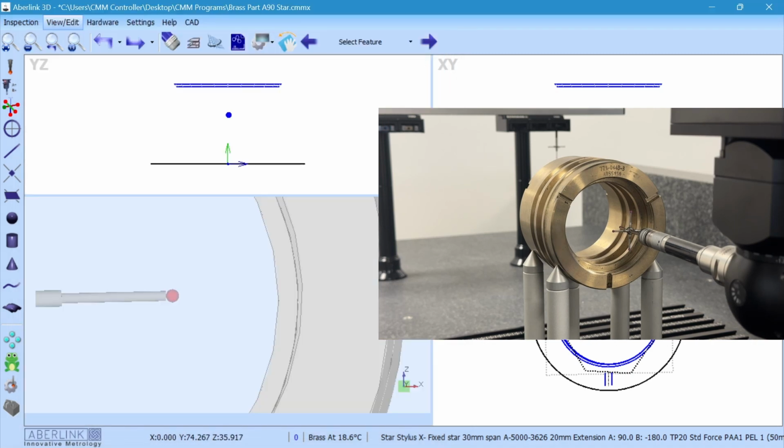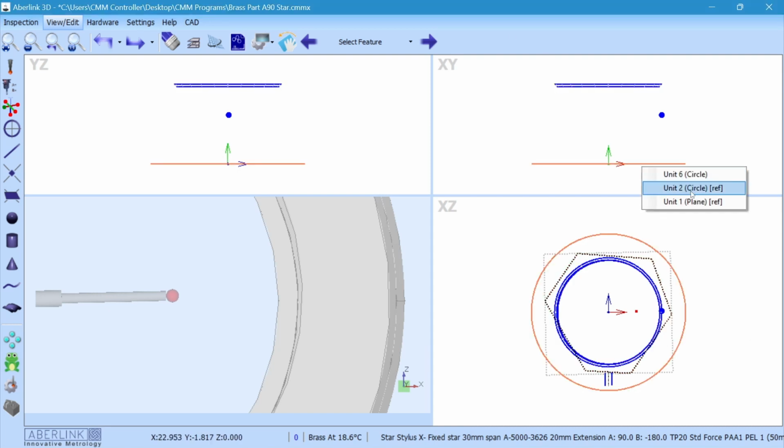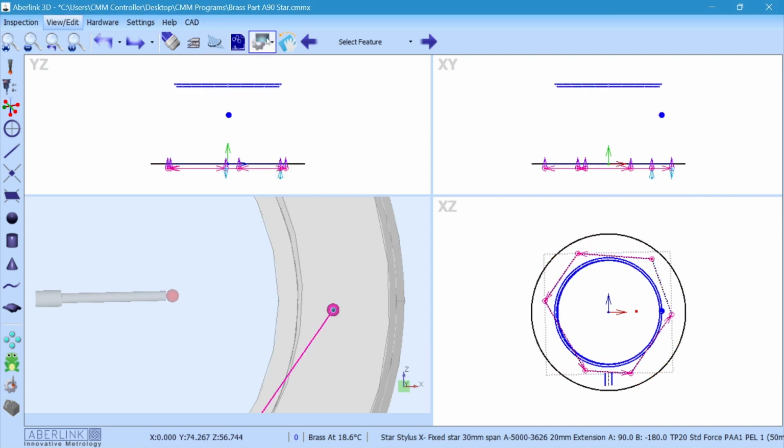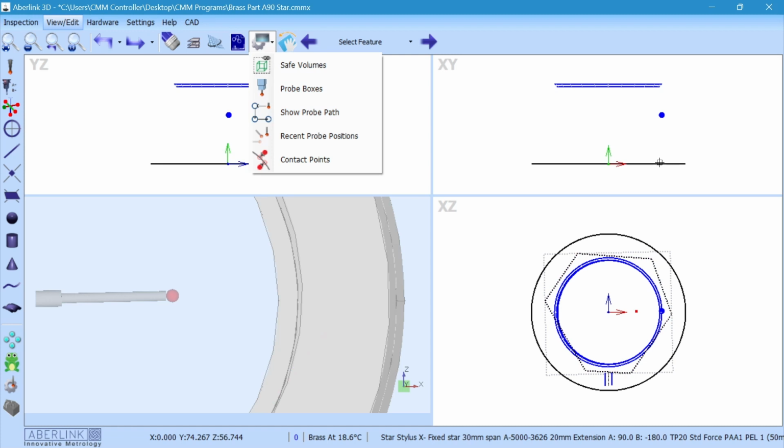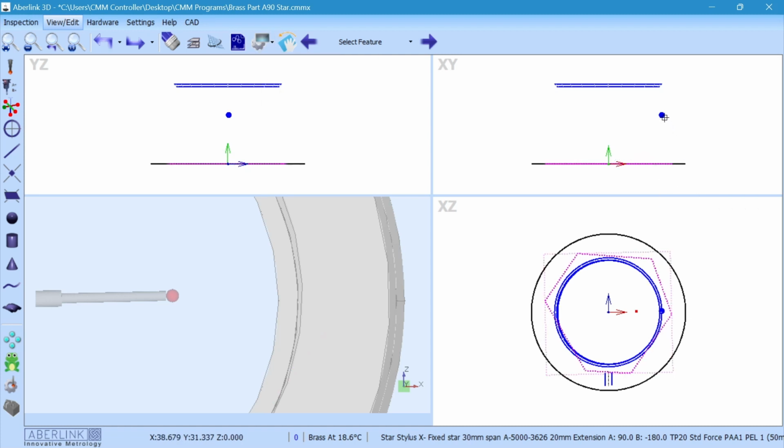If we look at that in the software now, we can easily go from the front plane to the point. Again, I just need to switch the probe paths off here. So front plane to the point, and you see we get a nice distance there. It is just a single point distance, however. If you need more data, so flatness, parallelism, squareness, as well as an average over the entire face, you have to measure it as a plane, and we'll cover that in the next video.